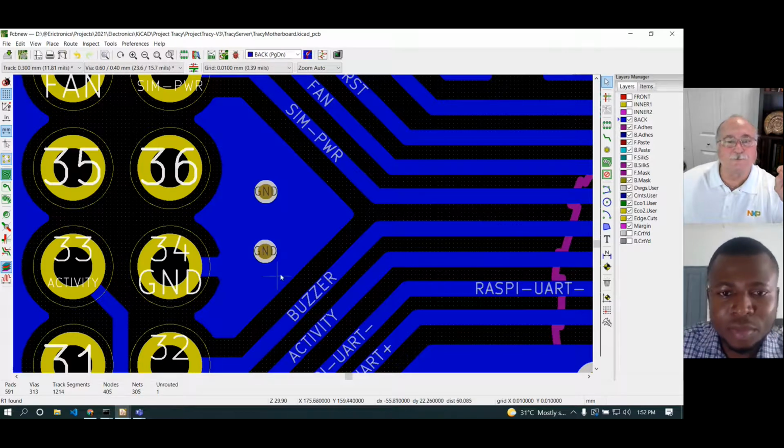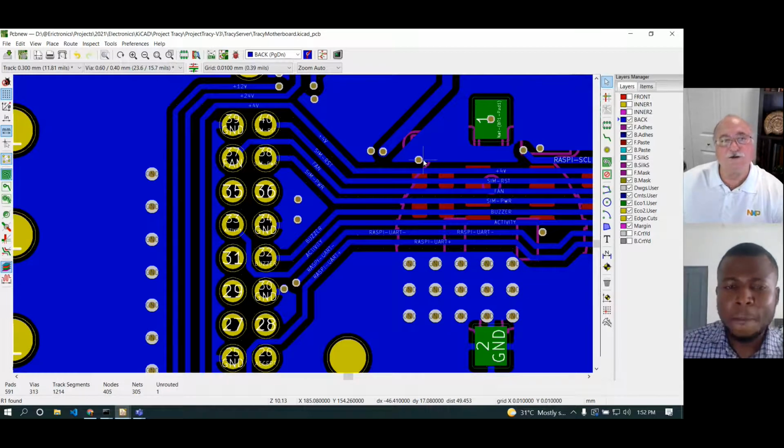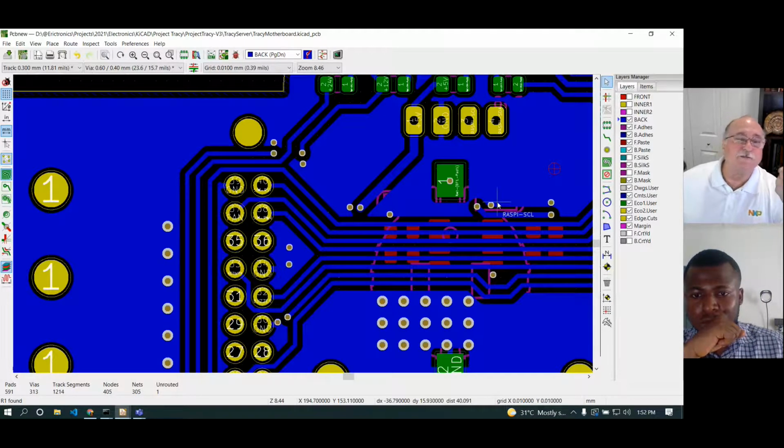And just to repeat, we talked about what causes crosstalk. When a signal is being driven through a transmission line, at the wavefront you have a changing electric field. A changing electric field will create a changing magnetic field in the signal trace conductor. It does also in the plane, but the plane is physically so large that the amount of magnetic field created is very, very small.